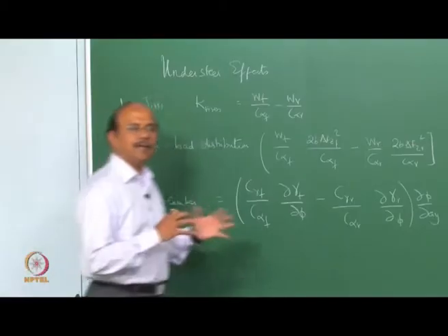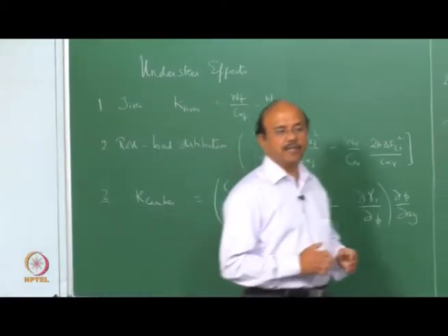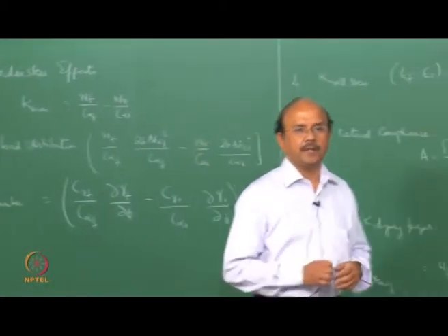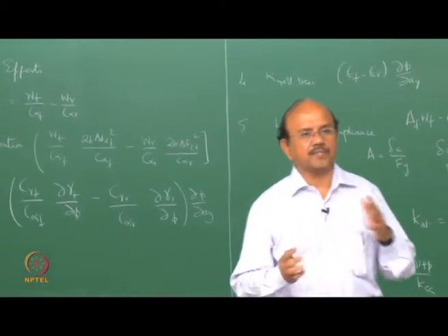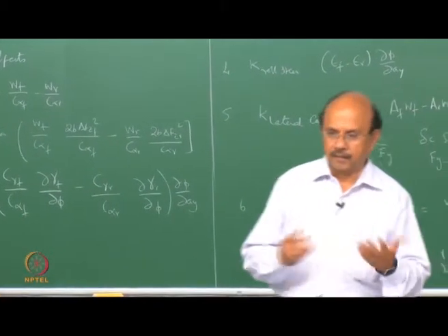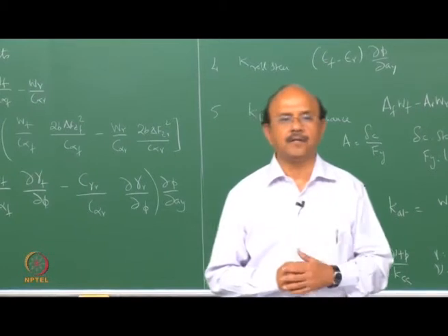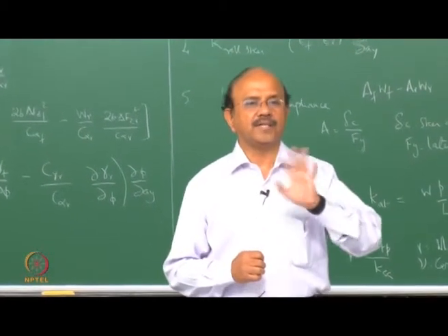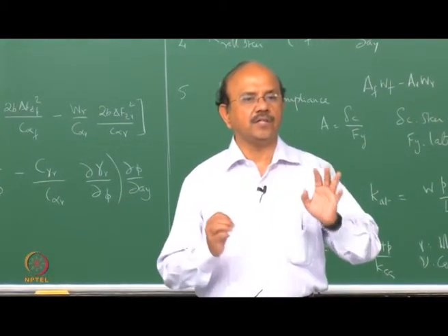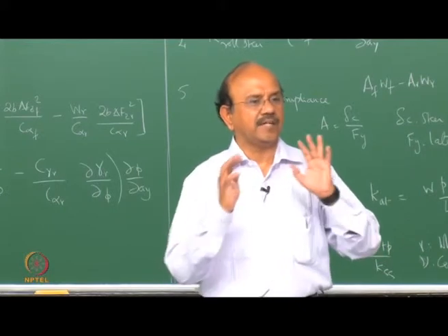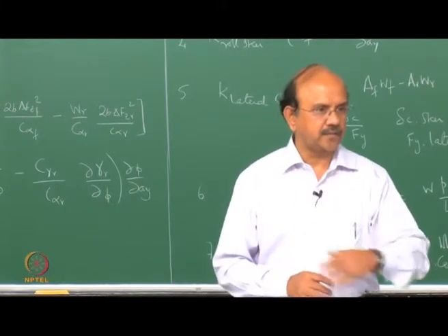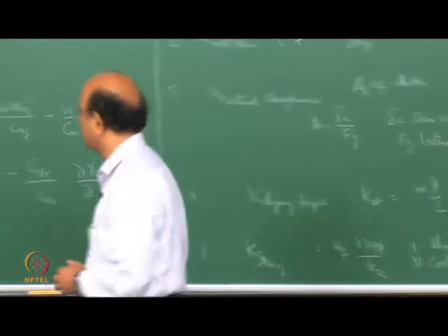We found that the nonlinearity with respect to Fz of the tire is going to cause a change in the alpha, the slip angle front and rear, and so roll would cause a change in the understeer, oversteer characteristics of the car. We saw that with the derivation.